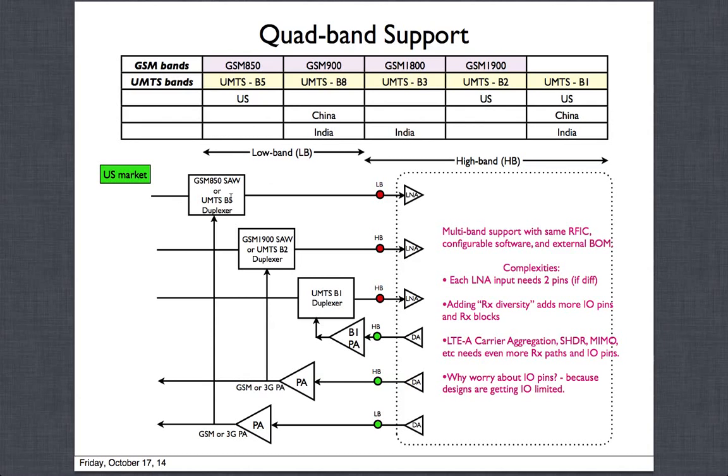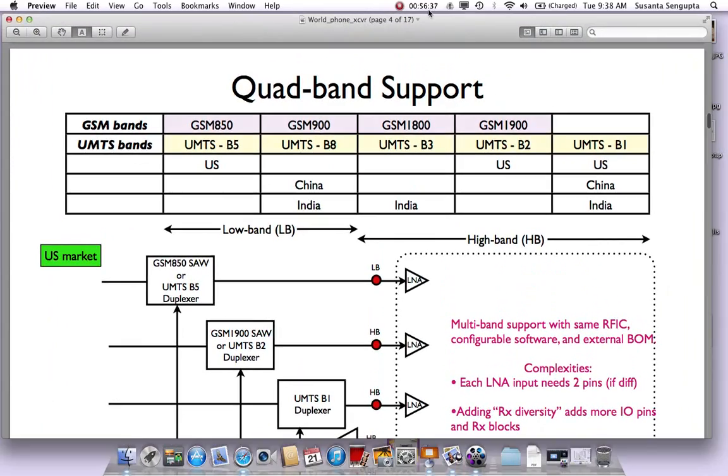But when you're doing the 2G GSM type, where the receiver is on and the transmit is on, the SAW is the filter that is trying to filter out the faraway blockers. If you could do a SAW-less design, where you can handle those blockers by doing intelligent things in the design, that is one of the things that a lot of the folks in the industry are working on, the SAW-less transceiver designs. So I just wanted to make a point on that before going to the next section.